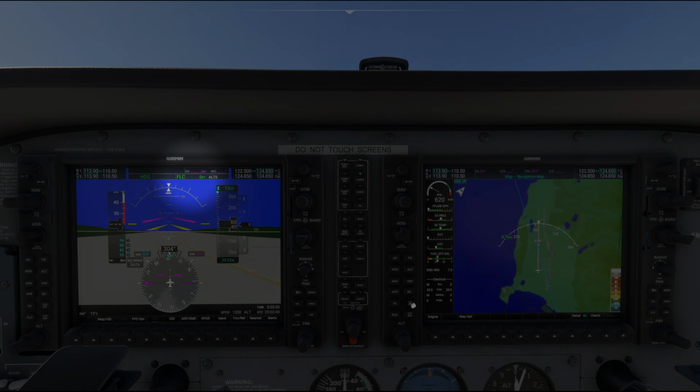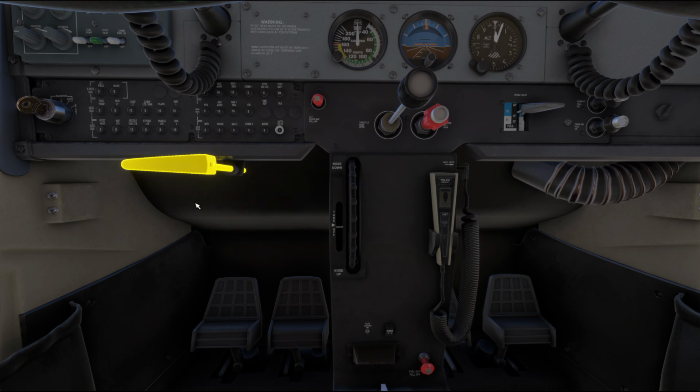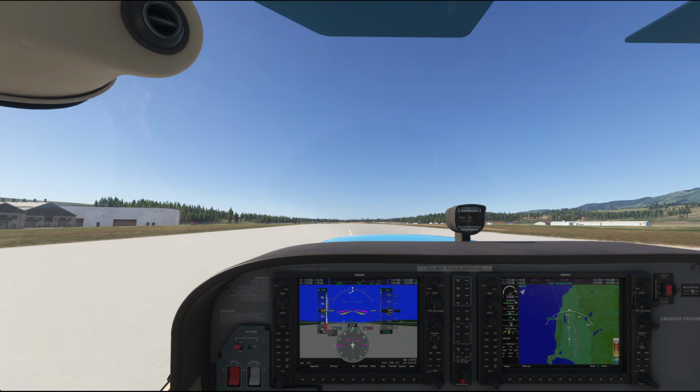You'll see PIT change to FLC and it will show 0 knots. Now use the nose up button to increase the target airspeed. For the Cessna 172, VY is 74 knots, so that's what we'll set. The white ALTS indicates altitude capture is armed, not yet holding. Let's release the parking brake, advance the throttle, and start the takeoff roll.